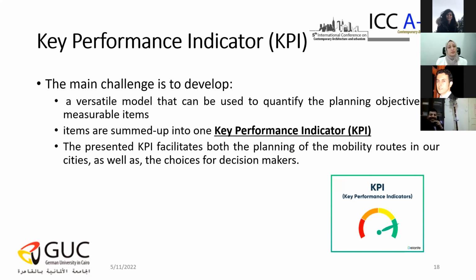Key performance indices are used in transportation, but they are always used to measure the performance of the network. Like, for example, the volume to capacity ratio, when we see how many vehicles are moving, let's say 600, and the capacity of the lane is 1,000, so 600 over 1,000 means it's less than 1, so it's not over capacity, so that is a good transportation system.